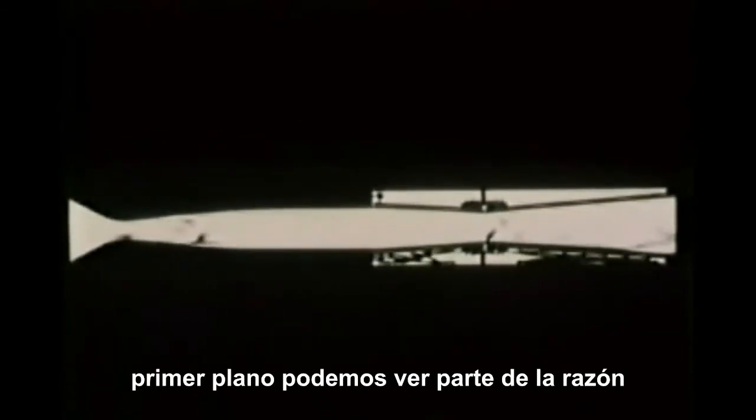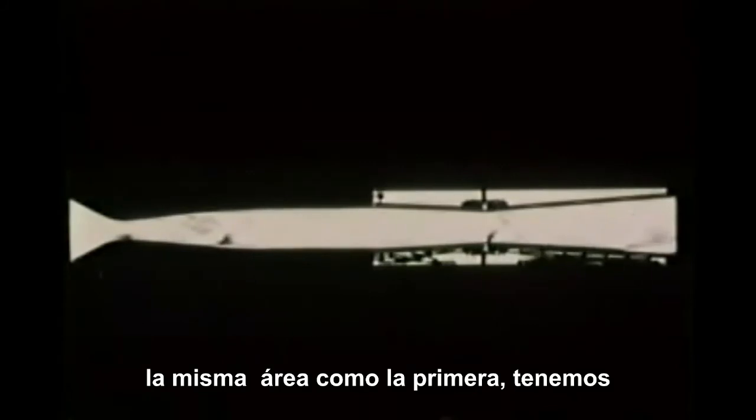In this close-up, we can see part of the reason why we cannot close the second throat to the same area as the first one. We have to allow room for these thick boundary layers, which are not carrying their share of the mass flow. As we vary the area of the second throat, notice the wave pattern changing in response to the slight motion of the walls.